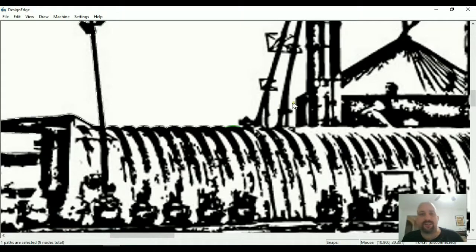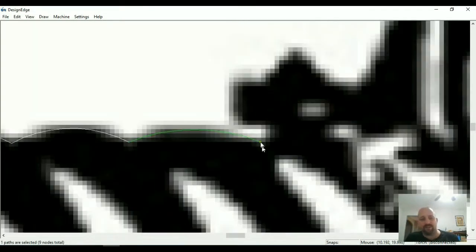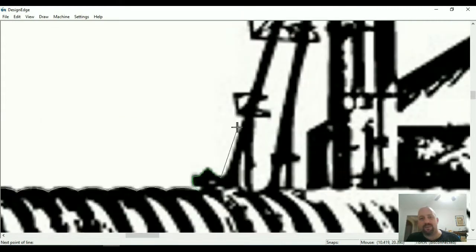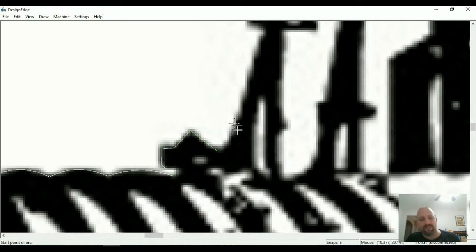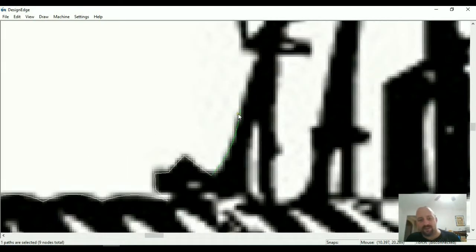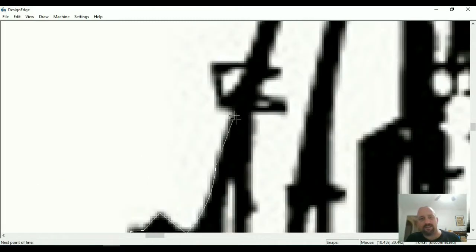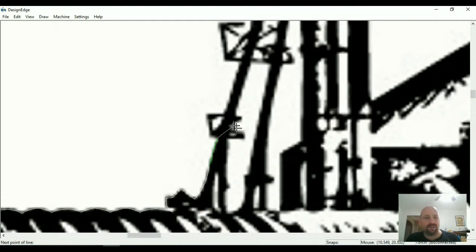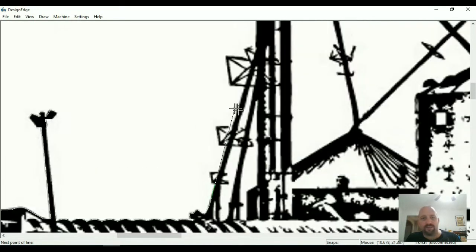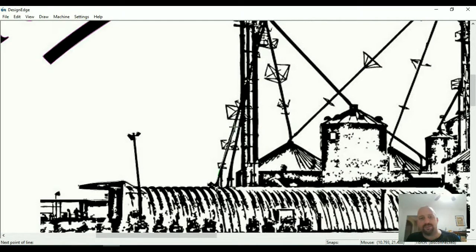in here. And I'm E endpoint snapping every time, so now we're going to have to go up. So L, snap it to my E endpoint, and we've got us a grain elevator piece. That's kind of a curve. Z to the E. So you see I'm using lines and curves. L on the E. And see, those are braces or what they are, but I'm going to skip those.